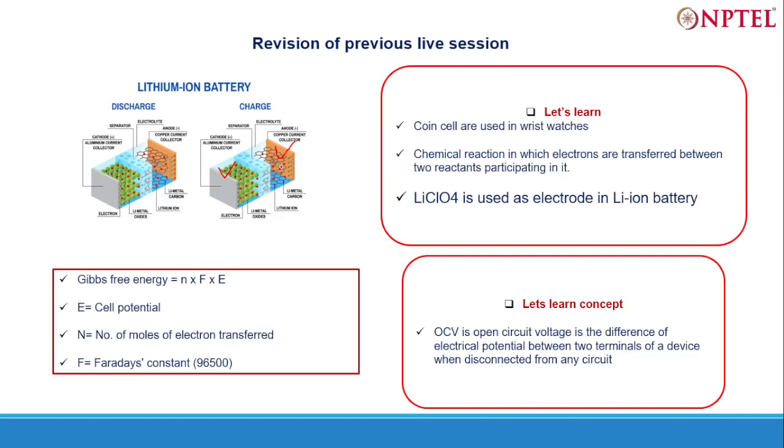So remember, the current flows through the outer circuit, the ion flows through the electrolyte. So there is electrolyte, the ions flow through it. And also what this separator membrane does is it selectively gives permission to pass the ions only. If there are impurities, they will be trapped at one side, and some other ions or molecules cannot pass. Only the ions associated with the electrolyte or electrode will pass. So that's how this separator membrane is designed.